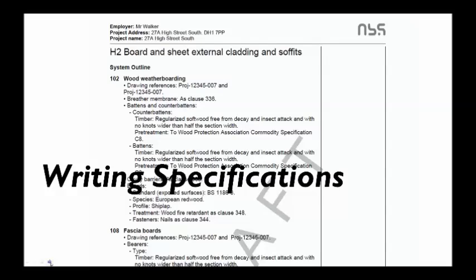Like if you're pouring concrete, there's not a concrete pouring truck that you get off the shelf at Home Depot. That's something that has to be done customized on site. So then instead of writing a proprietary specification, you would write a prescriptive one that says, okay, when you pour the concrete, it needs to be this temperature outside, and the ground shouldn't be frozen, and it should be this mix, and all this kind of stuff.